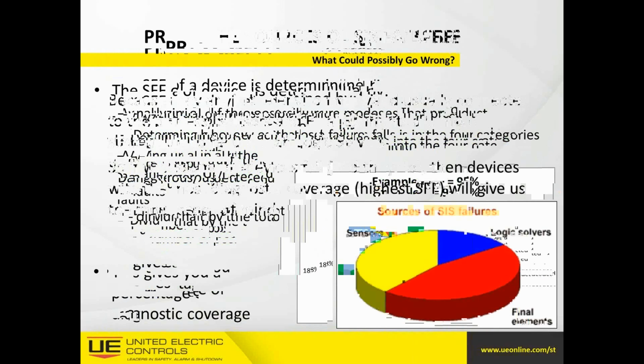Hey, Scott. Yes, sir. One of the questions that came up is that somewhere in there you said the product would have a SIL rating. I think what you really meant is, and this is very difficult to get the wording right every time, that Exida gives you a certification on the SIL. Well, yeah, I even just screwed that up. They give you the SIL certification that gives you the safe failure fraction that gives you the SIL level. Correct. And you've got to try to get the word rating completely out of your vocabulary, even though that's a very tough thing to do.